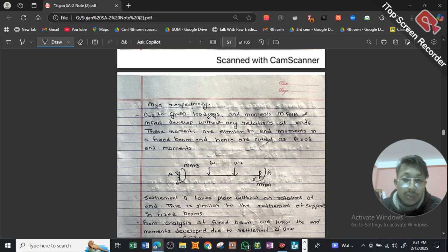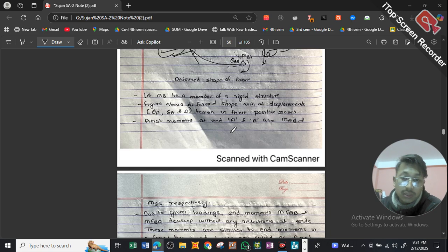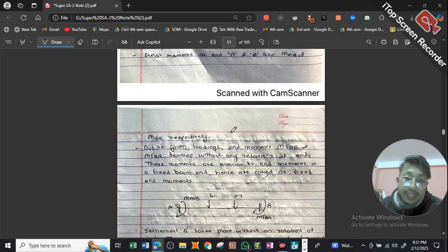Due to the given loadings and moments, despite these final moments, there will be fixed end moments as well. So we have our final moments. This is one thing. Next we will have our fixed end moments as well. These end moments are denoted by MFAB.